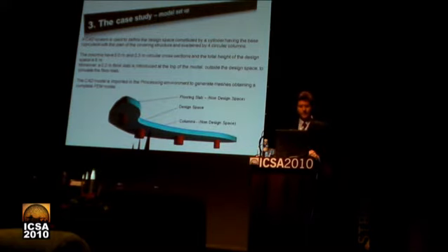So the first point is to define the design space, that is in light blue. The dark blue, the flooring slab, represents no design space, so we have a normal structure on the cover. The design space is the area where the topology optimization will work, and the columns are no design space, so we work only on the light blue volume.